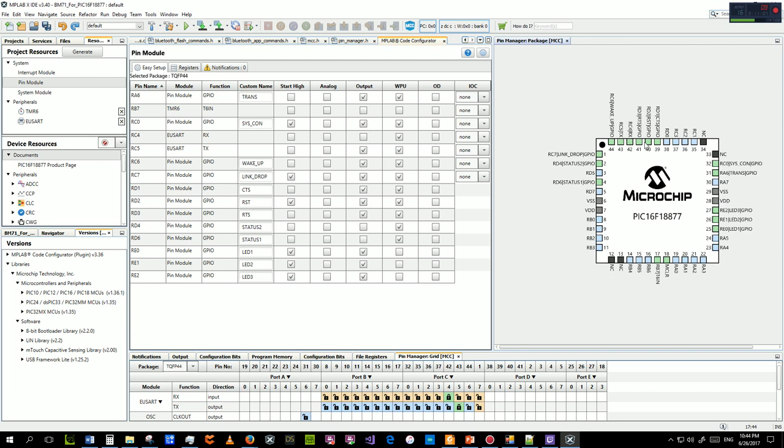So in reality, my wake up pin I cut into the RTS wire here, and this is actually the wake up pin, or the TX indicator pin on the Bluetooth module. I bring this up because if you look at the C files, that's Bluetooth app commands, you will see one of the commands where I send the RTS pin low, and then I put it high again for 3 milliseconds, as I talked about in the other video.